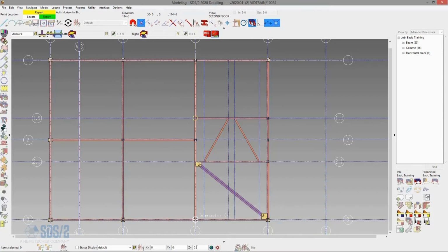So I can make this offset from Z plus to -3. I can also click on these buttons that say Z plus, and I can make it equals. In this case, I can say 114'3", and then no matter what I snap to, my Z is always 114'3".